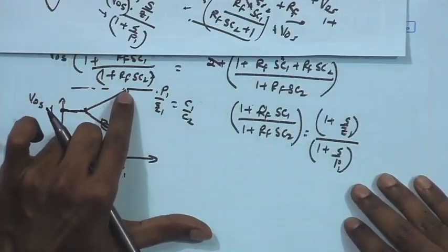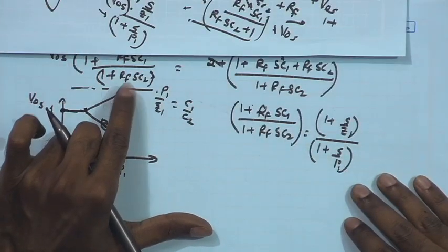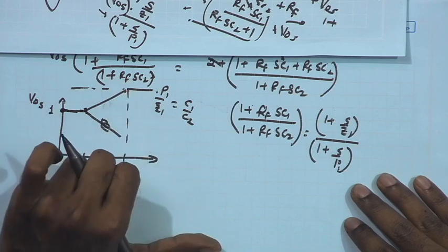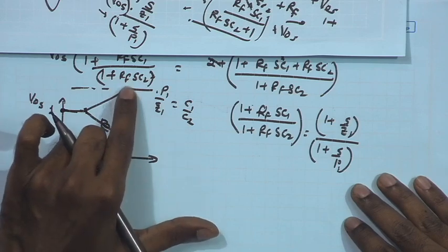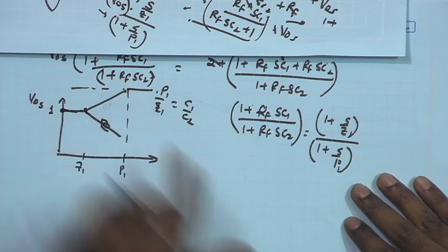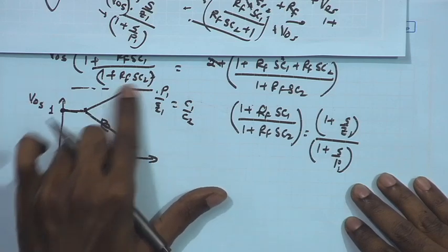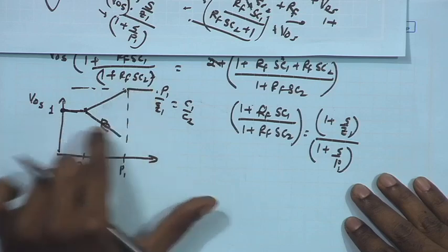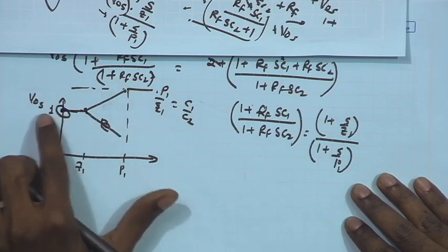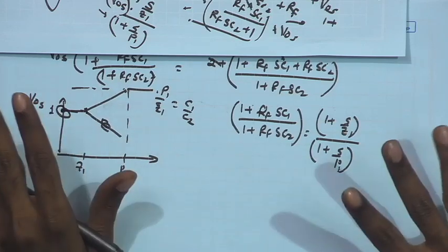So, while determining the transfer function, we have anyway seen that this P1 is determined with the help of RF, such that the overall transfer function is able to pass the lowest signal frequency of content, and our offset is sitting over here. For that, the DC gain is just 1 for the feedback configuration.